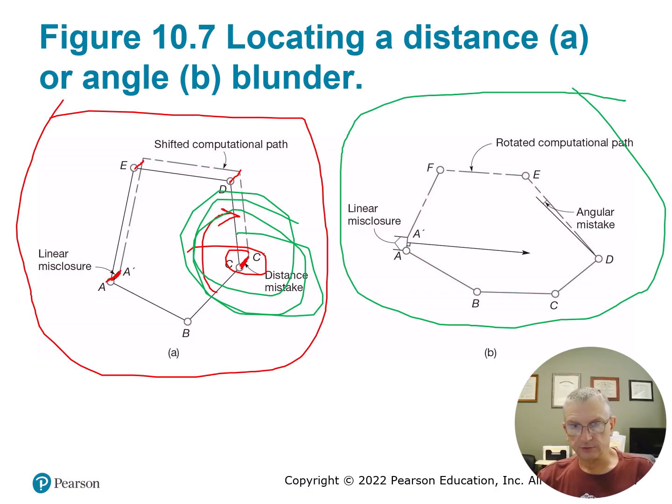And that's the illustration I've used with employees for decades: when you set up on D, and you've got this angular error here at the end of your traverse, this is where it is. It's the same thing as this angular mistake right up here. This same angular mistake here is going to play out at your closing coordinates. Let me go to a different color.